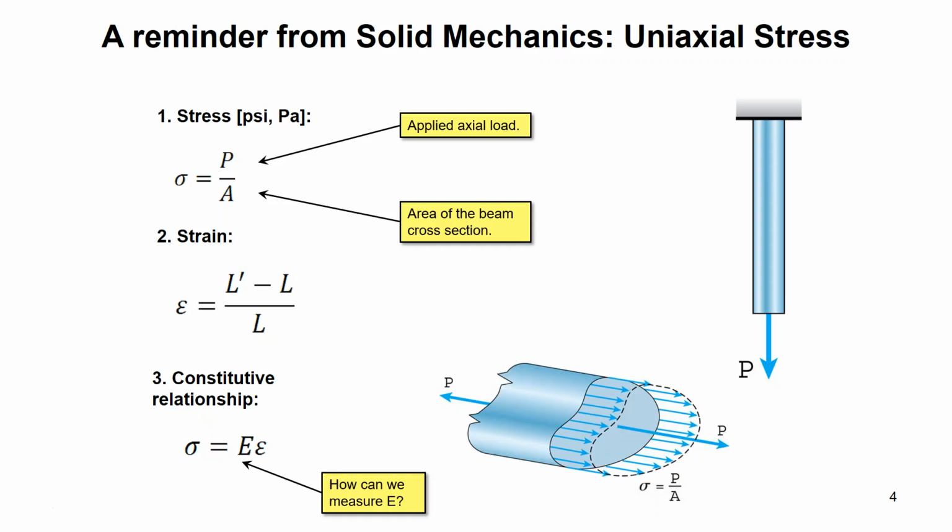So strength is a natural inherent property of the material, like steel has more strength than aluminum, for example. Once stress is below the strength, the part typically is okay. Once the stress surpasses the strength, is getting bigger than the strength, that's where the part starts to deform and then ultimately fail and break.